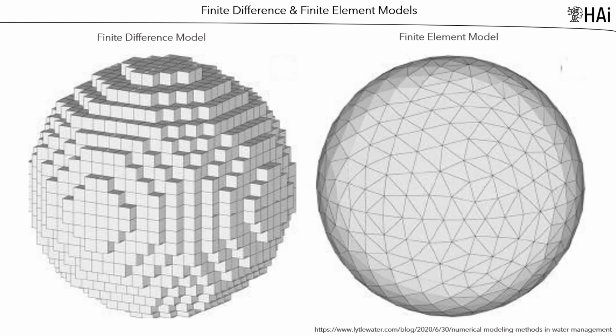The finite element model, FEM, consists of a mesh with irregular triangular (2D) or quadrilateral (3D) elements. An element in a mesh of a finite element model can be compared to a cell in a grid of a finite difference model. Different from a FDM model, in a FEM model calculations are carried out on the nodes, which are the vertices of each element. Due to the flexibility of a mesh, the model can represent the exact geometry of an irregular model shape. Furthermore, the discretization can be refined locally around the area of interest. This approach can achieve higher accuracy, in exchange for higher computational effort.